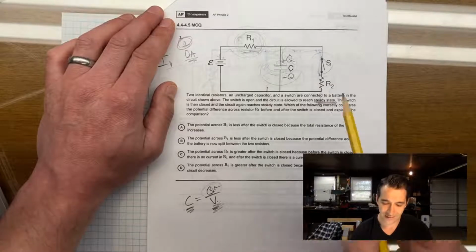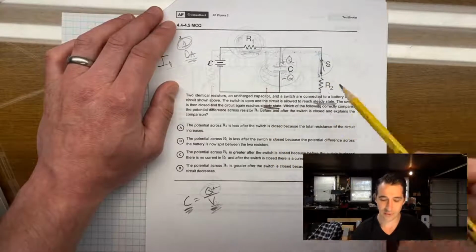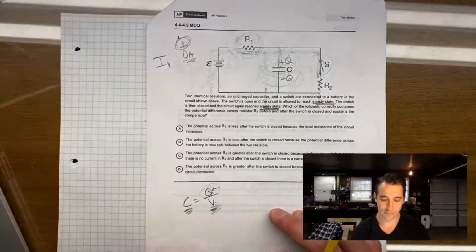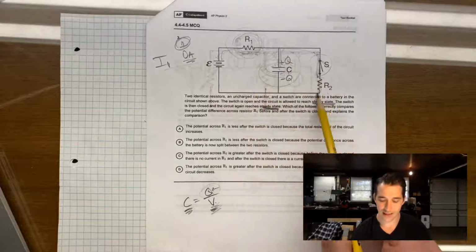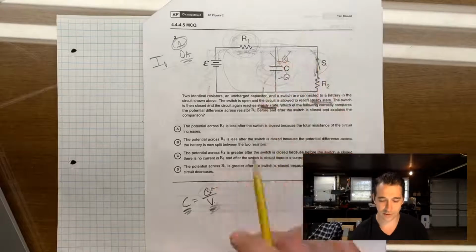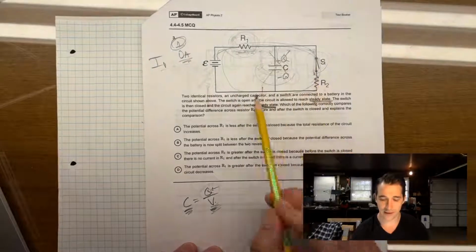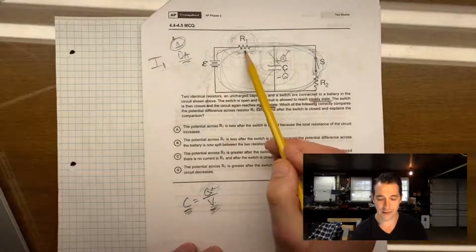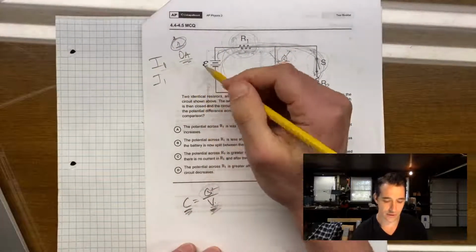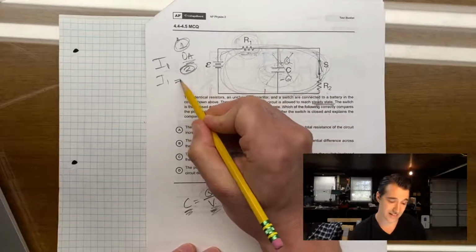But we don't really have to worry about that because at some point it reaches steady state again. And that's what they tell us. We close the switch, it reaches steady state again. Now once it reaches steady state, now current can flow and it's just flowing around the outside. Steady state means this part of our circuit is no longer involved. Current's not going through there. It's fully charged, whatever that is, and now current is flowing around the outside. And it's flowing in R1 and R2. So I1 in situation 2 has some value. I'm just going to say it's not equal to 0.